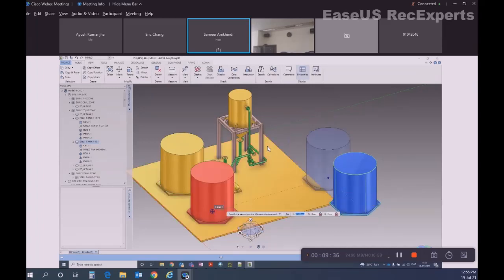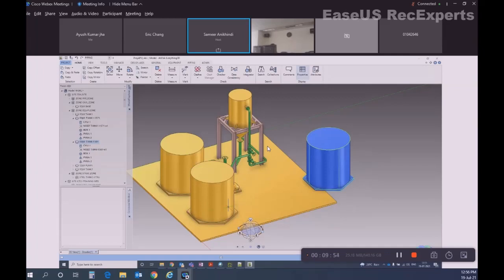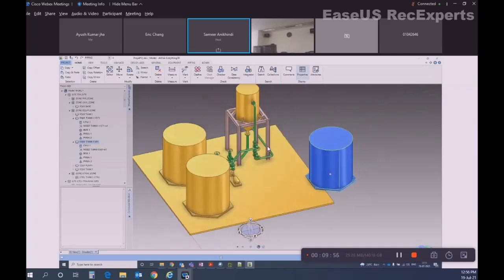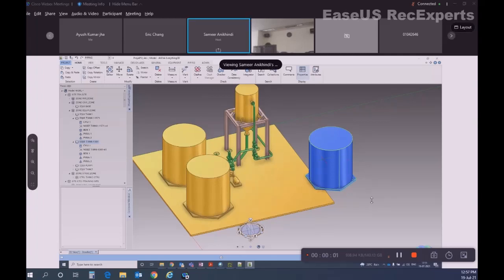And to pick the easting, I will just pick this one. You can see it is showing a ghost image, a translucent image, before even moving. The dot is the actual position, which will be the final position, the dot on the right hand side. You can see the easting is matched. This is the trick to match coordinates. So move and copy is clear.